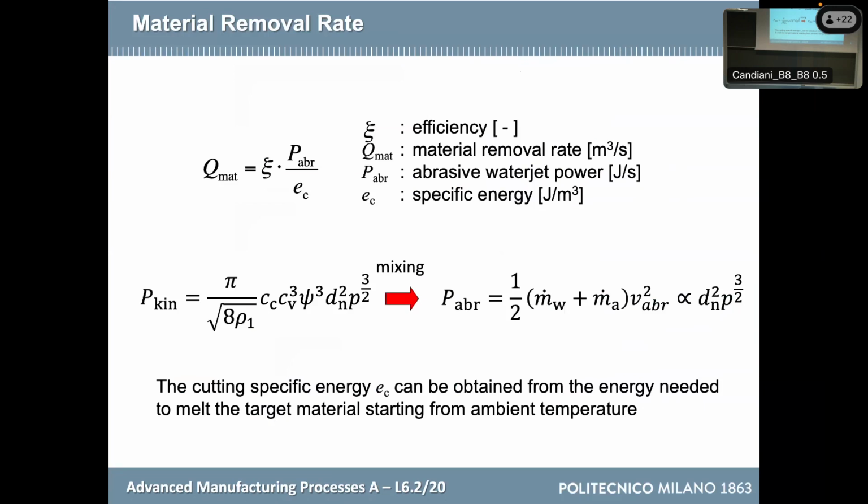We could do the same even for forming processes, where, if you remember that theory, we have a U, which is the amount of energy we need for deforming a certain amount of material. Now I cannot write, but if you remember the stress strain curve, also considering the plastic field, where you arrive at a certain epsilon, the area under that curve is a specific energy. So it is an energy per unit of volume, which is again comparable to this one. So we can compare processes.